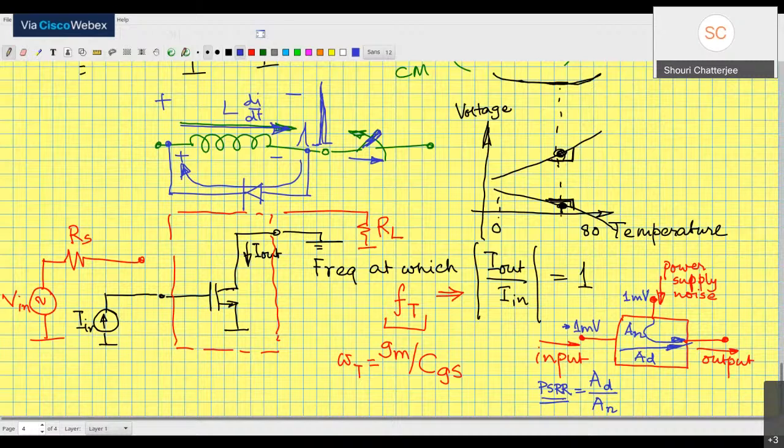Maybe it is coming from a rectifier. That will have some ripple, right? Maybe it is coming from a battery, but you're also driving digital circuits with this, and they are drawing power periodically, with the clock, and that is causing a drop in the power supply periodically. So that is causing digital noise to get injected into the power supply.